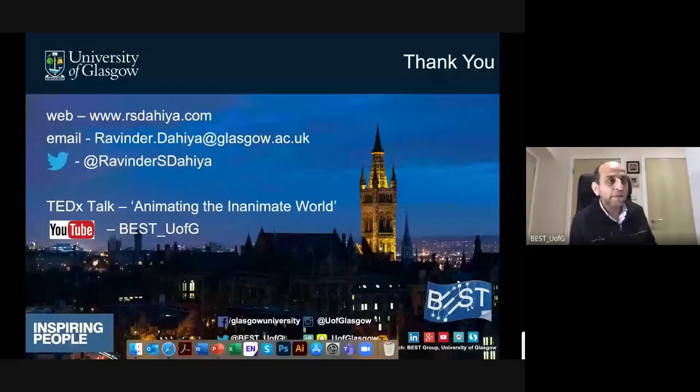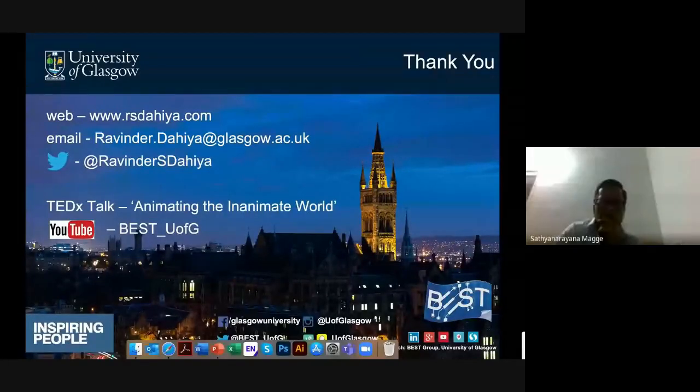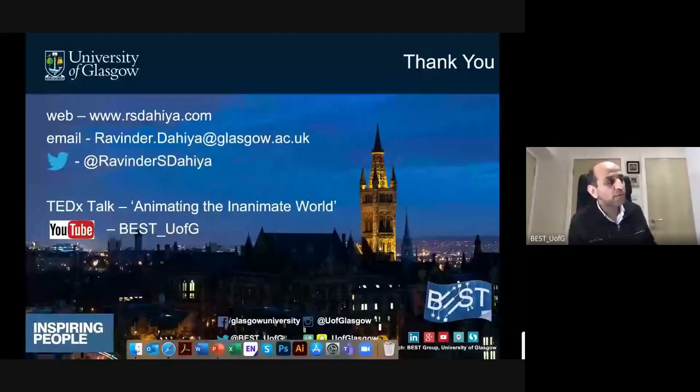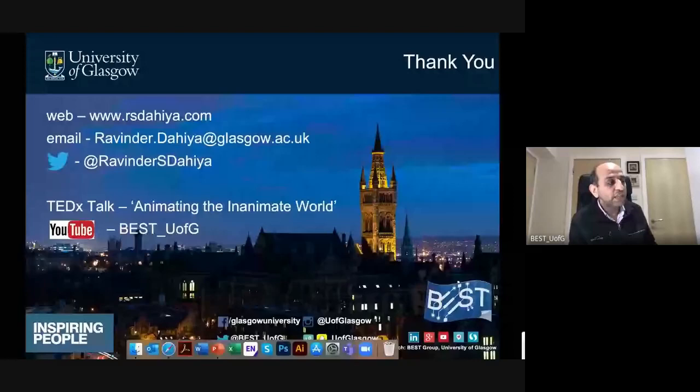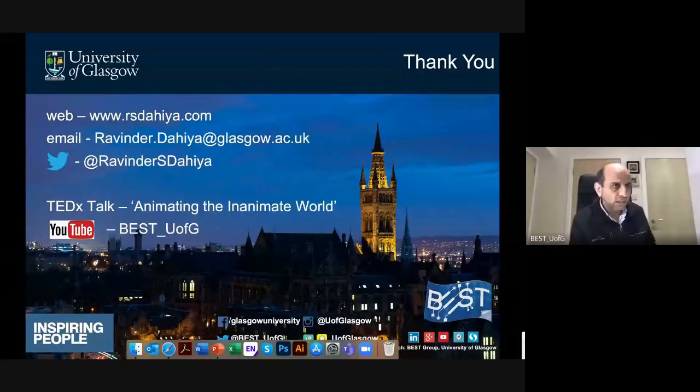You can integrate. So the time delay depends on the material again. If it is a soft material and quite thick, then it will take time to regain its shape. So there are various dimensions to that. Normally, piezoelectric sensors are very fast. The range, it's milliseconds, less than milliseconds response we have noted. So in those cases, we have not seen significant delays, but there are capacitive sensors where we have seen the response coming in the order of seconds also.